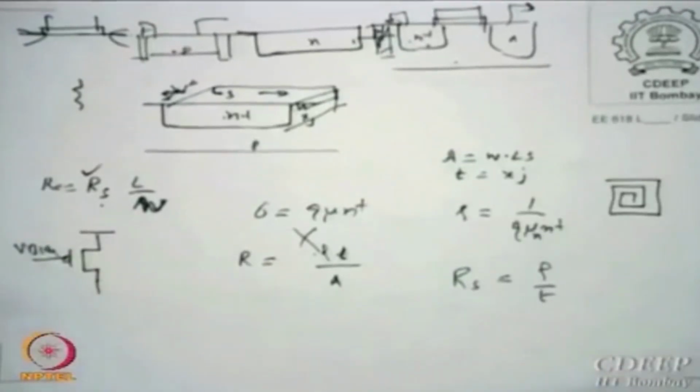A P device properly biased acts like a resistor. So I am not actually going to use any resistance anywhere. Is that clear to you? So please take it that in real life on a chip only MOS transistors are preferred everywhere. Convert as much as you can. Ground this, ground this, open this, do whatever, but that's all that I will give you.